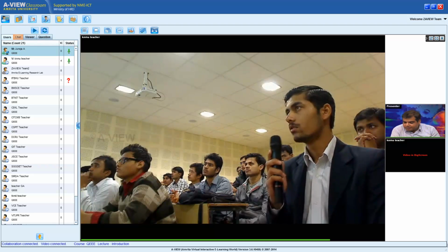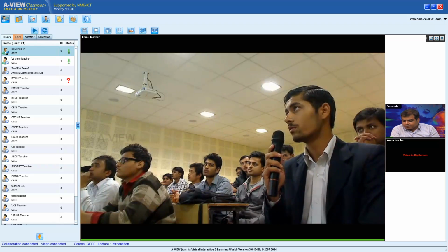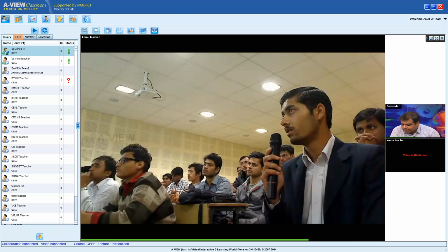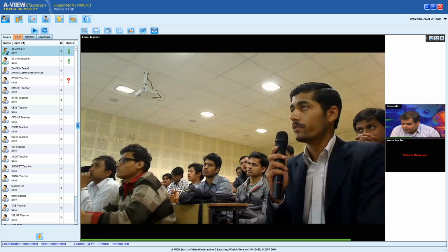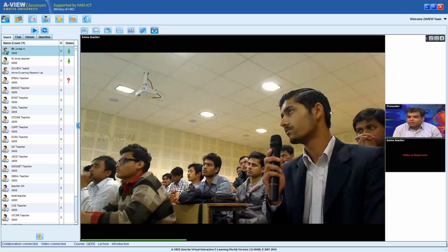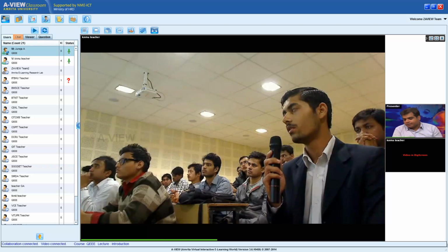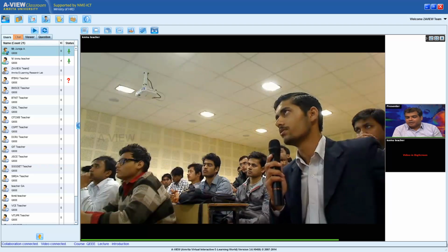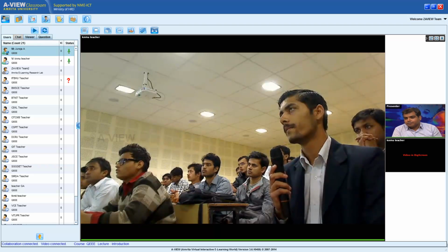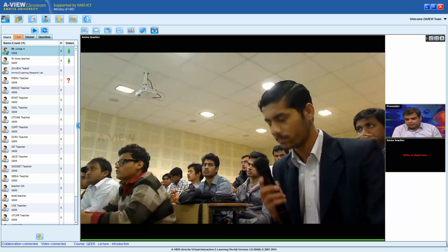Sorry, can you repeat your question? Hello sir, my question is what is the difference between the percentage of water content in both of the soils? The water content will be the same. In both the soils? Yes. For submerged as well as saturated soil, the water content will be the same. Okay, thank you sir. You're welcome.